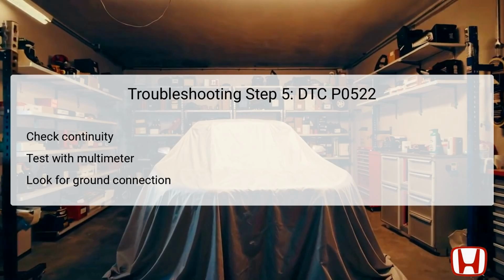Ensuring a solid ground is essential for the sensor's operation, and subsequent repairs may require addressing wiring issues or re-establishing good ground points. This step is fundamental in tracing the problem back to its source and ensures that the correct electrical signals are being relayed for optimal engine function.